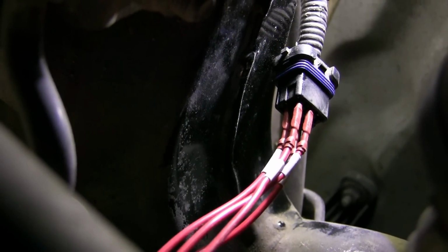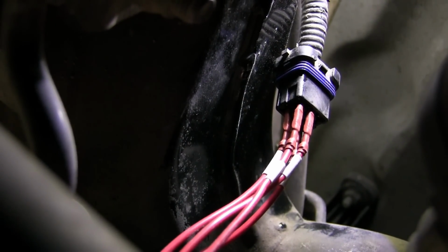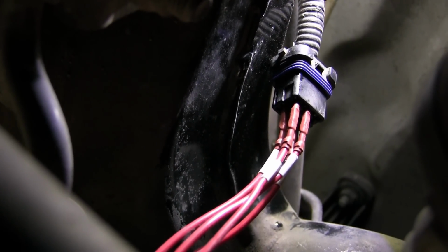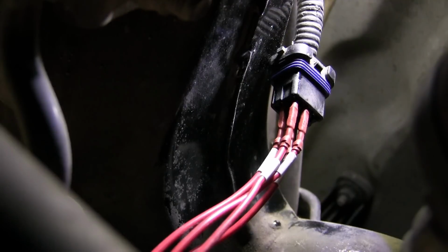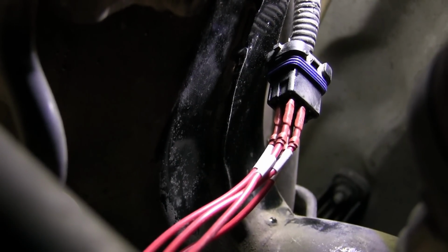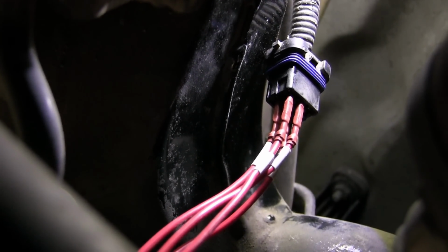Here's the CAN splice pack for the electronic brake control module in the rear. I've gone ahead and bridged it, and we've just taken out the bridge that would go to the brake module, and I've got it connected to the main bus. So if the scope shows a good waveform, the electronic brake control module is my problem. So we've unplugged the connector, and I've gone ahead and bridged that connector as well. So now the rest of the bus is reconnected, and the only thing that I've got off of that connector is the parking brake